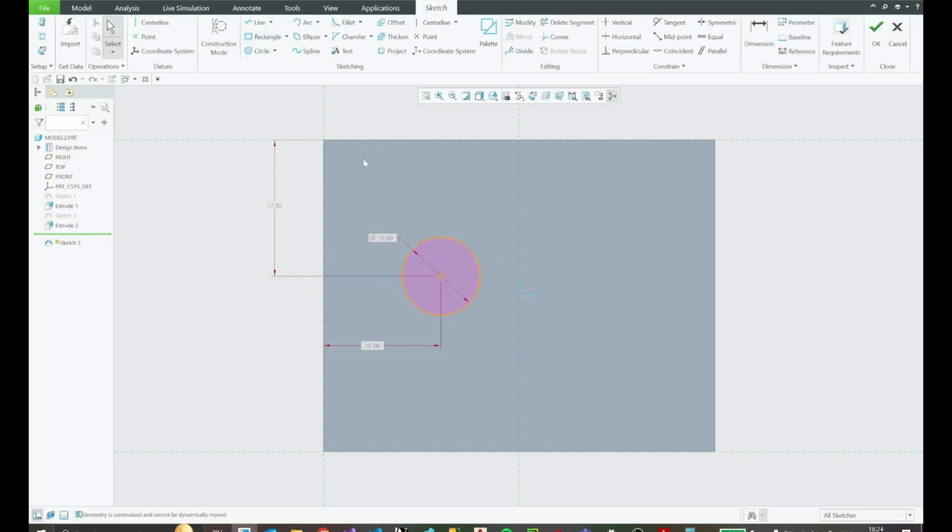So this is perfect. Go over here and then hover over the center of this circle, and then you can see a line, which means that they both have the same center in X direction, and then make it big enough. So you can see that the left circle is highlighted now along with this constraint symbol, which means that it's gonna equalize both of the radii of the circles, right? So if you click over here and press X, it's not gonna change the radius because both of them are connected with the equality constraint.